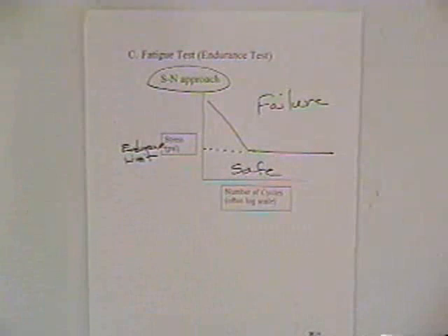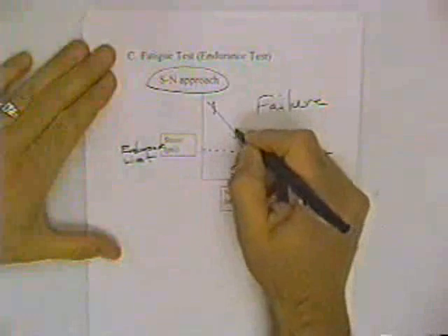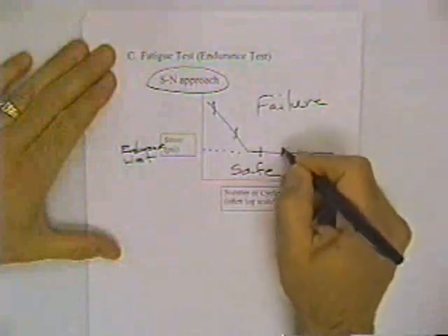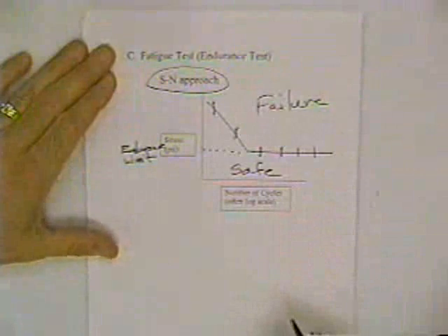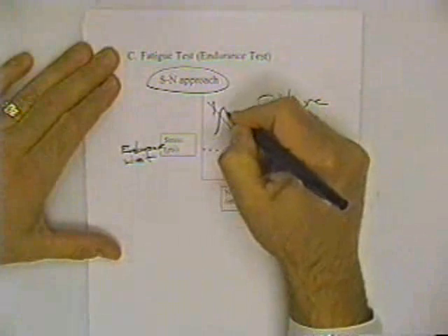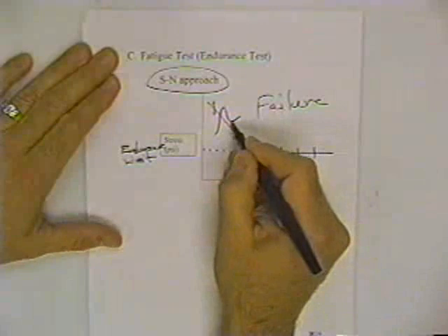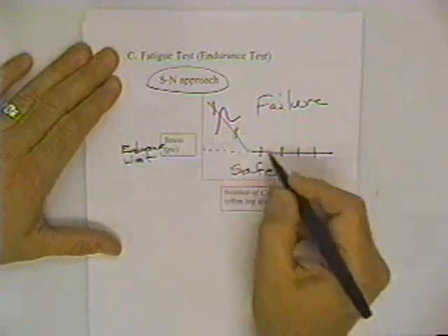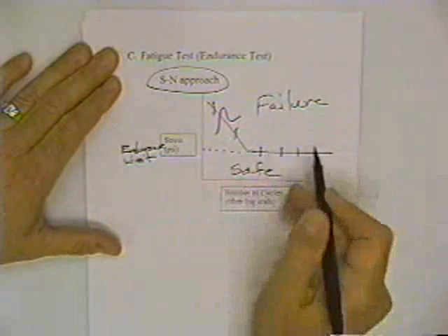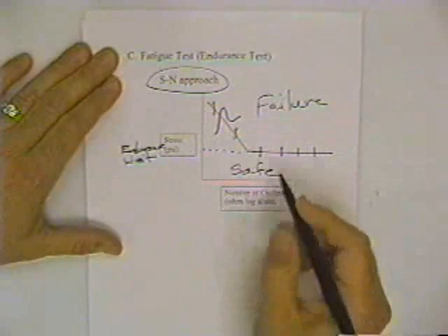Now, the actual fact is that if you have stress risers, corrosion, wear, there are a number of things that can lower that endurance limit. And also, I ought to really be honest, shouldn't I? This is really a band region, and there is some statistical nature to the fatigue process, where there are some specimens, a few going to fail on the high side, some going to fail on the low side. Usually you have statistics. If you want a 50% chance of it failing here, that would be the solid line.